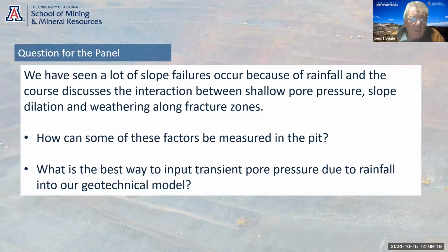And then the other thing is horizontal drains, particularly where we have fractures which are parallel to the slope. Relatively shallow horizontal drains are often important, and they may not flow for most of the year. They may only flow during or following a rainfall or a snowmelt event, and that's when you need them. You can actually think of them like the pressure relief holes in a retaining wall or a civil engineering structure. The same thing. They just flow when you have a buildup of pore pressure.